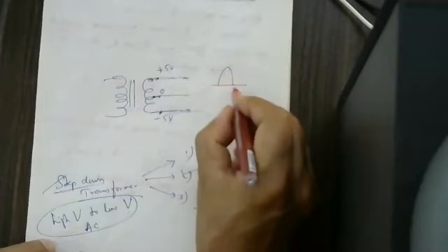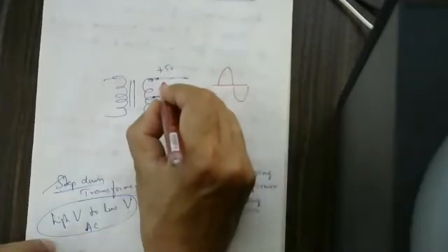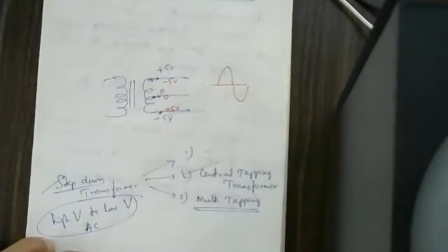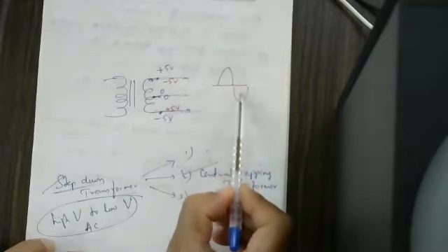Plus 5 volts to minus 5 volts, the difference is equal to 10 volts. Here to here, the difference is 5 volts. Here to here, the difference is 5 volts. 0 minus 5, 5 volts. 0 plus 5, 5 volts. Plus 5 to minus 5 volts, 10 volts. During the positive half cycle, this is happening. During the negative half cycle, this will become minus 5 volts. This is 0. This becomes plus 5 volts. Everything is reversing. This is what happens during the positive half cycle and during the negative half cycle.